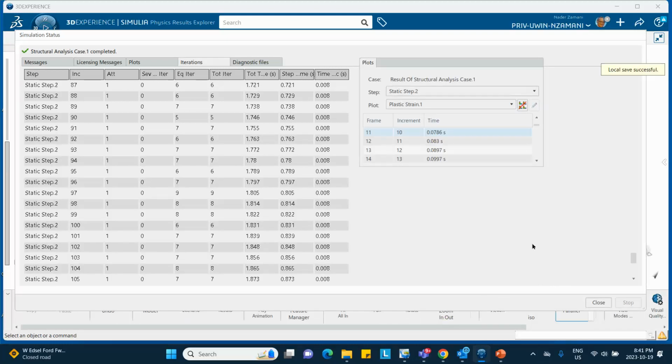Okay, I'm back. This thing took another 25 minutes to run. So here's the situation. In the first run that I made and showed you the results, I pushed that top to the right by 100 millimeter and rotated it 90 degrees, and then removed the load and the rotation. So that column springs back to a position which is not the initial position because of plasticity.